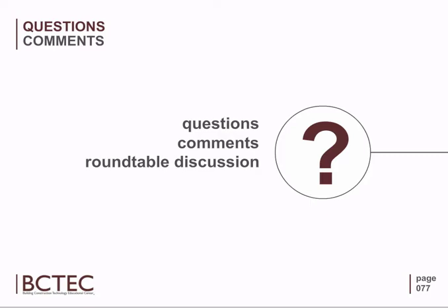And I'm super glad that question came up, because that's something that we want to talk about, roof inspections, and now's not really the time to do it, but there's a tool that we use all the time when performing roof inspections. It's a roof audit checklist. It's super simple. Goes through all the different components of the roof system. So the surfacing, the membranes, the flashings, the equipment, the drainage. Just a checklist that you can run through while walking your roofs and check off if you have problems, and really support in evaluating the overall condition of your roof.